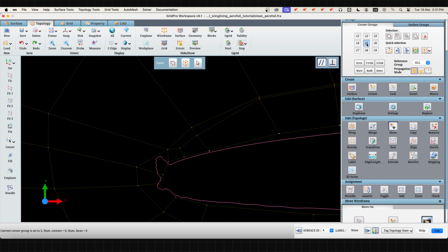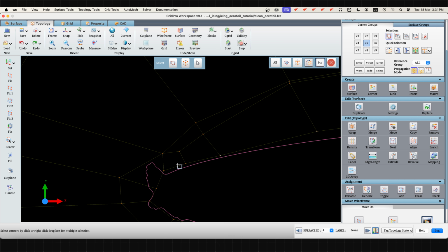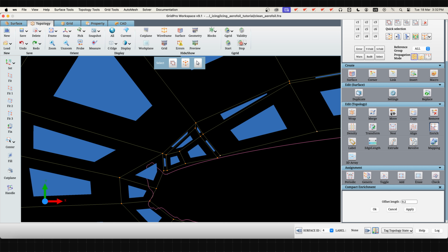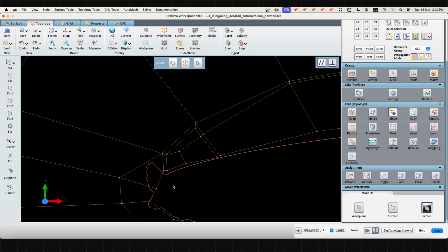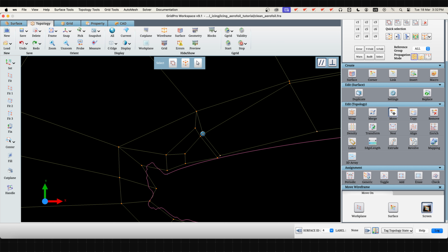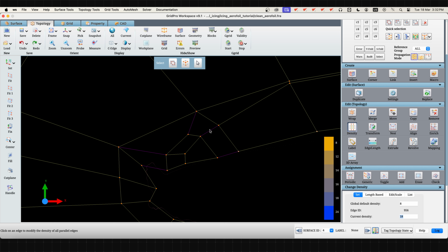We will use the corner creating 3-point singularity for compact enrichment. Group this corner in a corner group and apply enrichment with a value of 0.2. After repositioning the corners, we can see the internal wrap structure forming around the selected corner. Density can be increased in the wrap layer to capture the region better.